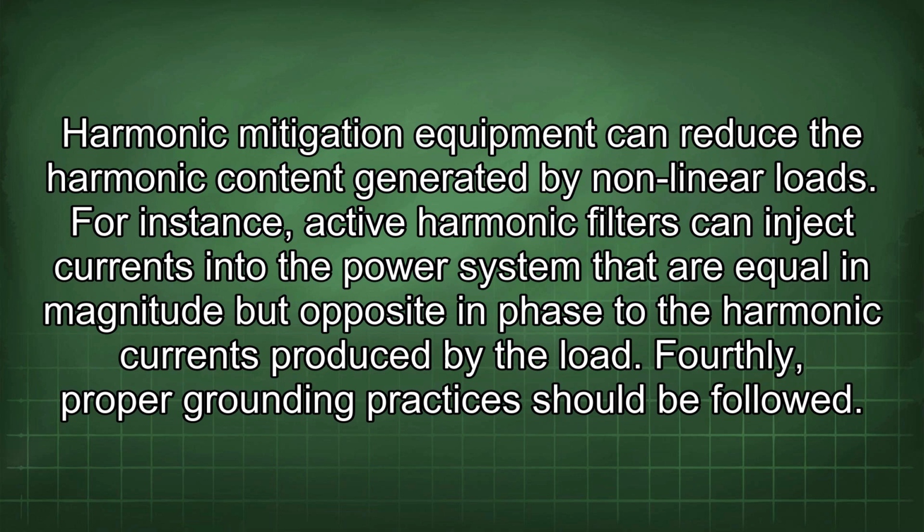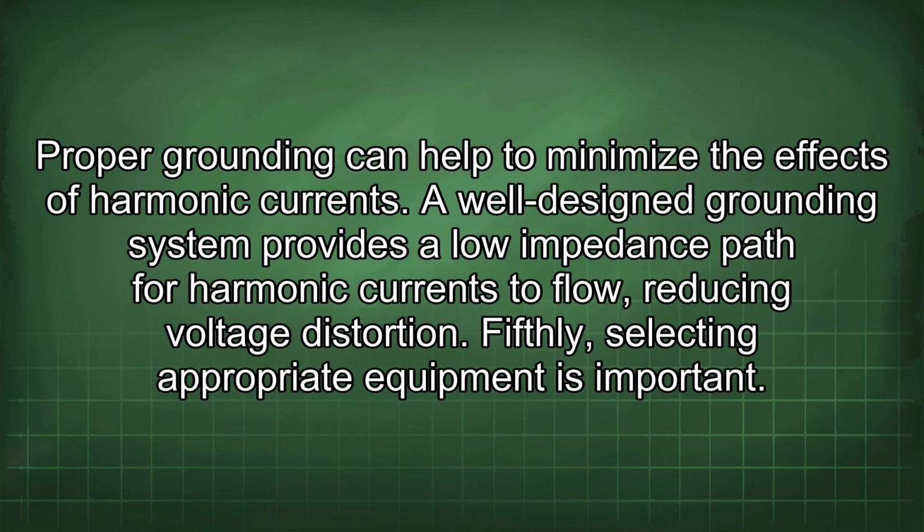Fourthly, proper grounding practices should be followed. Proper grounding can help to minimize the effects of harmonic currents. A well-designed grounding system provides a low impedance path for harmonic currents to flow, reducing voltage distortion.